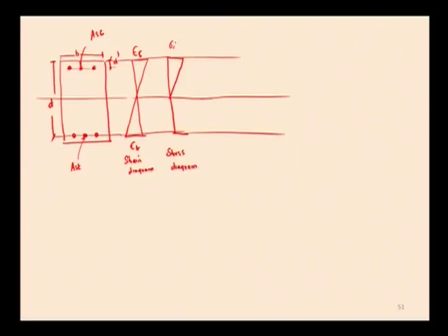So, maximum stress at the topmost extreme fiber is sigma cbc, and the stress at the distance d dash from the top is called sigma cbc dash, and T is the tensile force, and the equivalent stress diagram here is this one. This is the equivalent stress diagram obtained by transforming the area of steel into the equivalent area of concrete.